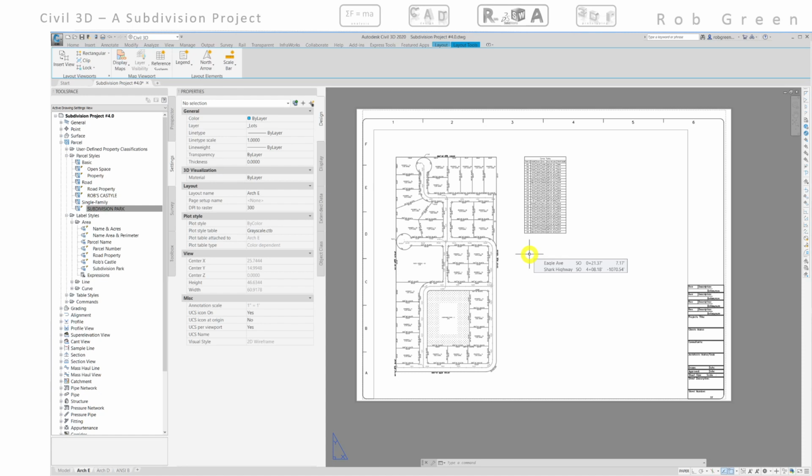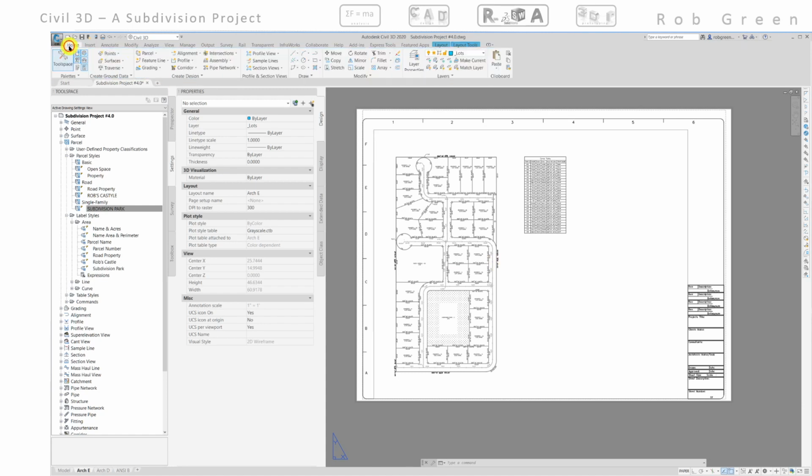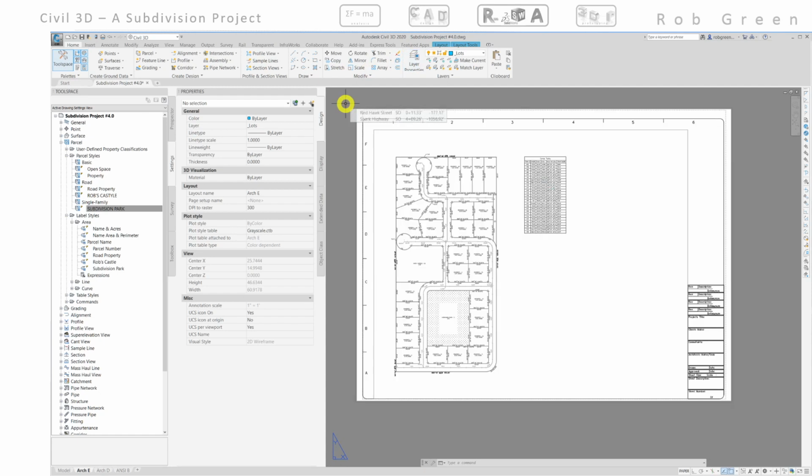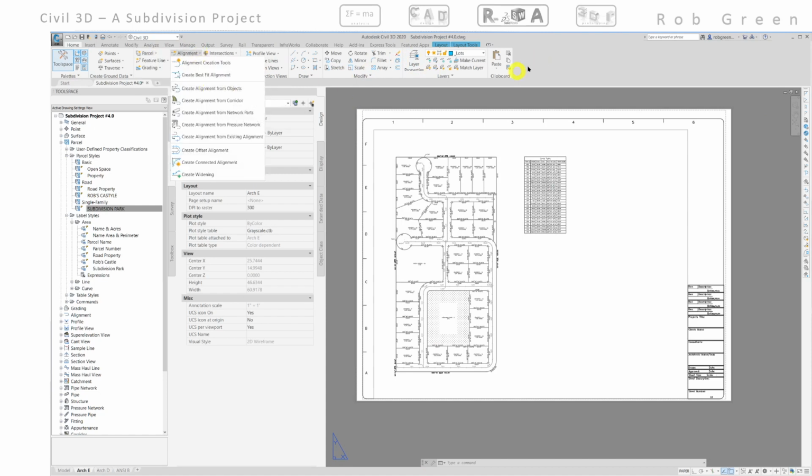So within just a couple weeks, we've actually learned and understand how to draw using our basic AutoCAD commands and our basic trim commands. We've learned that layer management is going to be handled by Civil 3D, except in our first section. And so it's important for us to create a few layers that we start with. And we have learned that in parcels, we can create parcels from objects. We can create alignments from objects.